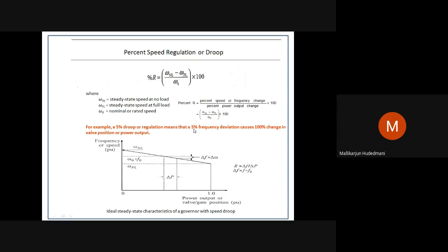If the frequency drops and a deviation is noticed, that is a stimulus signal for the governor to change the input control such that it operates to open the valve 100%. It means 100% opening of the valve is the signal from this ratio. So for every drop in frequency, there should be an opening up of the valve to bring the frequency back to steady state frequency.